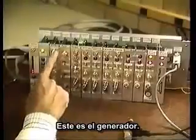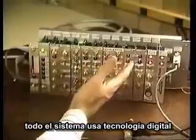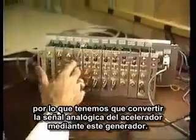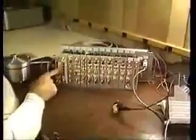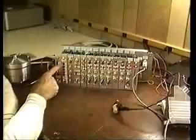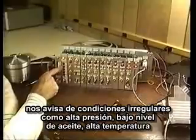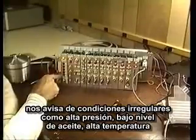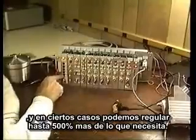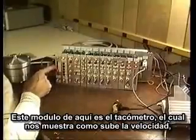This is the master generator. Everything in the circuitry is basically using digital technology. We do convert it to analog where we have to for the accelerator control. Over here we have an alarm module. This module will give us an overspeed trip if the tach goes too high, or if we have high pressure, low oil, or high temperature. And in some cases we put a jar switch on there, because, like the Indy 500, that is a requirement. This module here is our tachometer module.